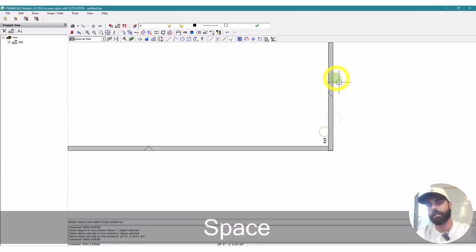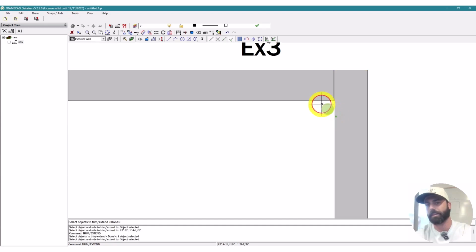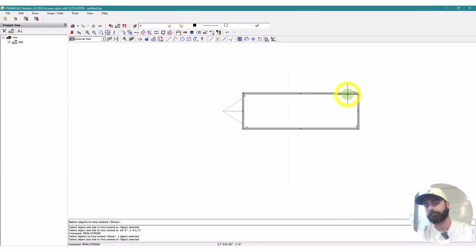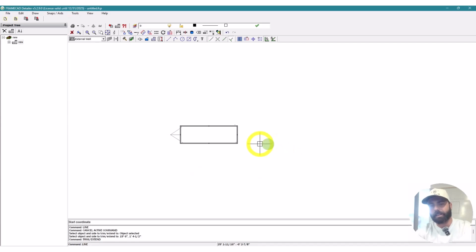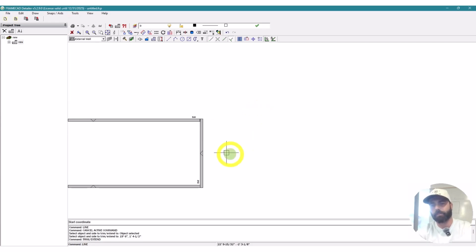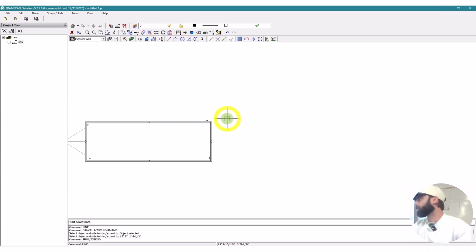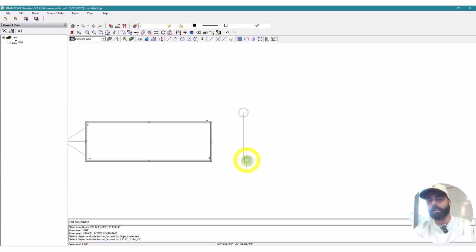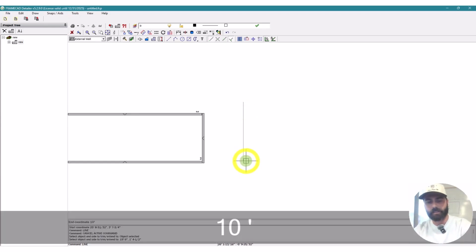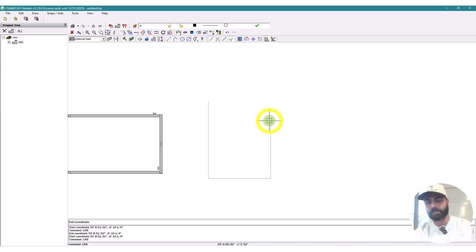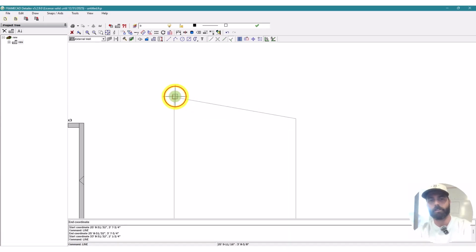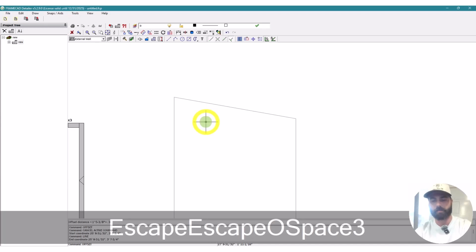If you're designing in Rhino, or if I'm designing in SketchUp, then I'll often draw the wall profiles myself as I'm going. The other thing that I do really quickly is create references for myself. A tiny house is 24 inches off the ground. That means you can have roughly a 10-foot 6-inch tall wall. We're at 8 feet, and then on this tiny house we'll do a 9-foot short wall. I'll offset this by 3 5/8 of an inch.